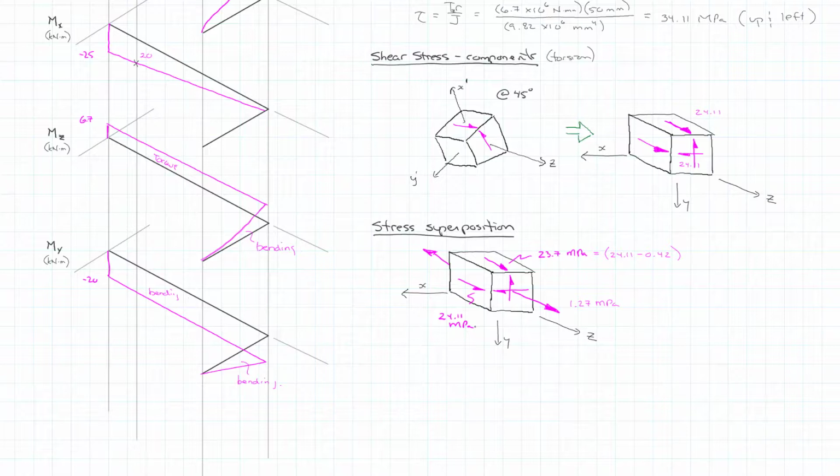Now, I'm not suggesting that this is exactly the way that I would solve this normally, but I thought it was worth going through so that we could see that complexity of three dimensions integrating and working together. As you start to go to more complicated structures, you're going to have to flip back and forth between what we call global coordinates and local coordinates, because we would normally do these diagrams in a local coordinate system for the member itself.